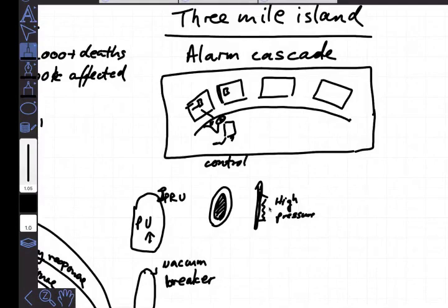But that control room typically is not fitted with windows, and depending on what you are making on the site, if it's a really dangerous chemical, the control rooms will be blast proof, and in many cases they'll have a double door system so that operators can go in and out. The upshot is that it is very difficult for operators to know what is going on outside of the control room.